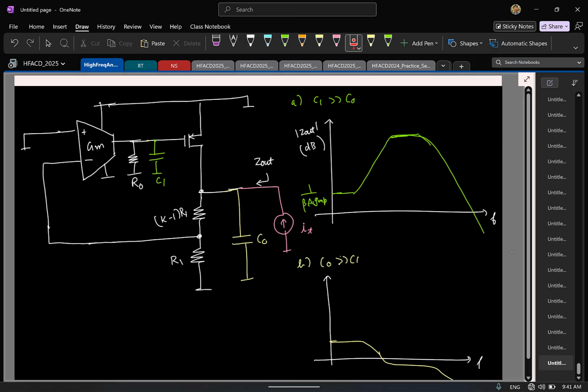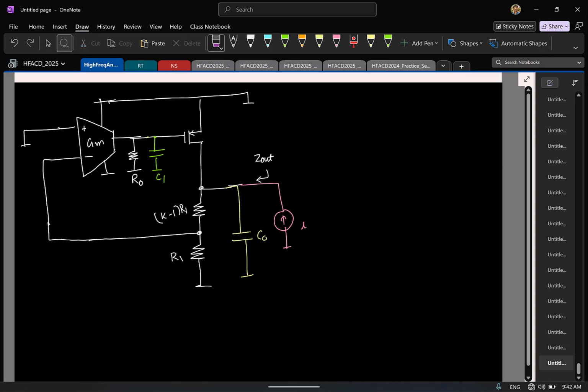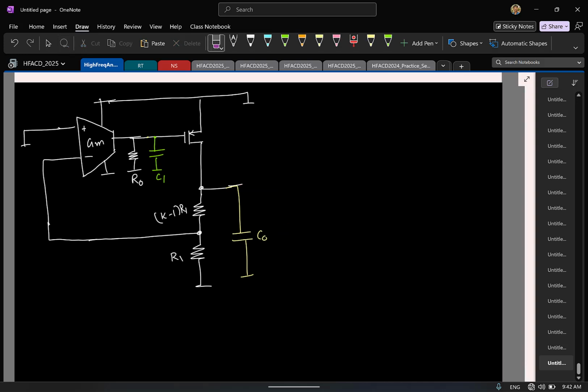Okay, so now let me just mention one other consideration here. With respect to LDOs, another important consideration is this. The idea is to keep this output voltage constant irrespective of any changes in the circuit. Which means even if I have small signal disturbances on the supply here, my small signal change here should be what? 0. That's what I should expect. And this is called the power supply rejection ratio. So let's briefly see what will happen.